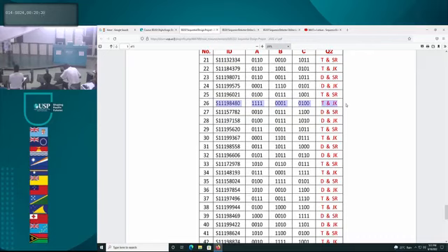Now, T and JK. Let me repeat that example. Let us say you need 5 flip-flops. You calculate and find you need 5 flip-flops. How do you do that? In that case, one will have an odd number and one will have an even number. It's your choice: 3 T's and 2 JK's is fine, or 3 JK's and 2 T's. Somewhere around the half and half mark, but obviously one will have an extra because of the odd number. Please take note of this.